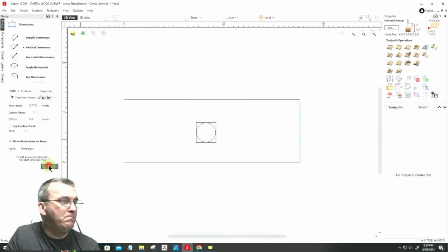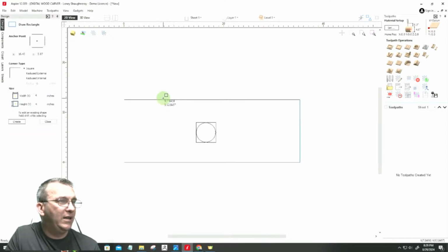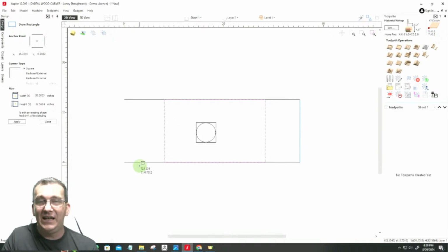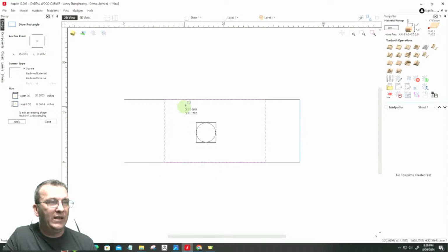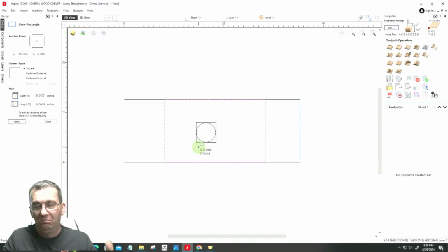And I'm only milling within, let's say, as an example, this area here, and this needs to stay square blank, that needs to stay square blank, and I'm not able to cut into it, I can't round it off and turn it back to square or whatever the case may be. I just need to leave it alone. Then I need to work within this area, right? I need to have a boundary laid out like this rectangle here. And all of my tool paths, I need to machine within that boundary, right? So the bit doesn't go past that boundary. Okay.